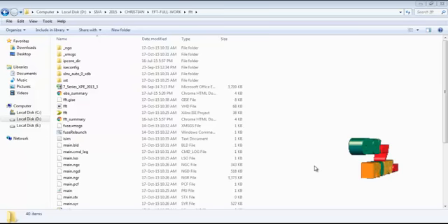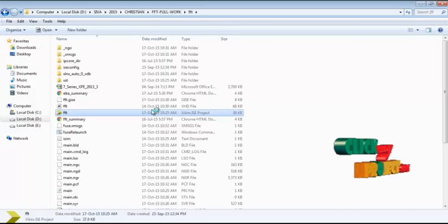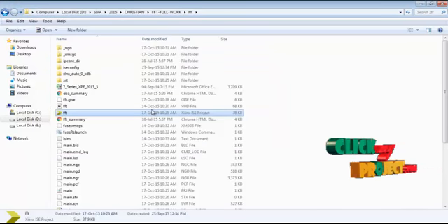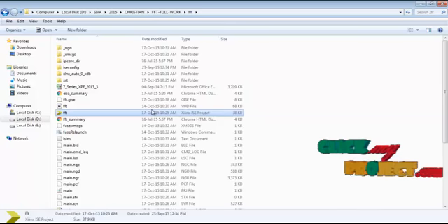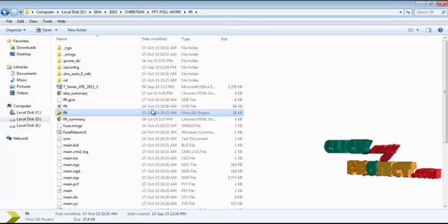Finally we see the output for the product. For our overall FFT architecture, we run the Xilinx ISE Project Navigator. Our process was developed in the VHDL language, using Xilinx 14.2 software. Then we open the ISE Project Navigator, which analyzes the simulation and synthesis performance results for the overall FFT architecture.